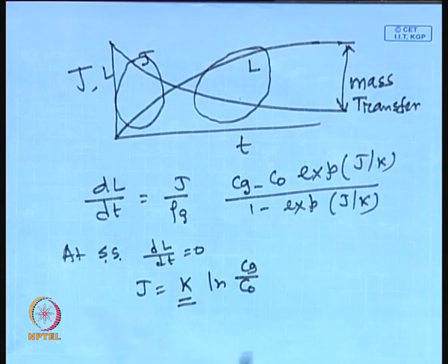Now if you look into the various parameters, it is very difficult to get the exact parameters like alpha, that is the specific gel layer resistance, epsilon g, that is the porosity of the gel layer, and particle size, particle diameter. Now there is a point in this particle diameter dp, simply because we are using the Kozeny-Carman equation from the filtration theory to quantify alpha, or the specific gel layer resistance or cake layer resistance, but this particle diameter dp in the Kozeny-Carman equation is valid if you have hard spheres, right.